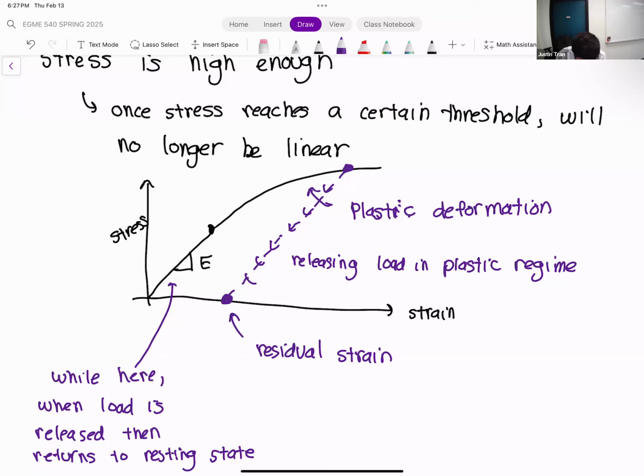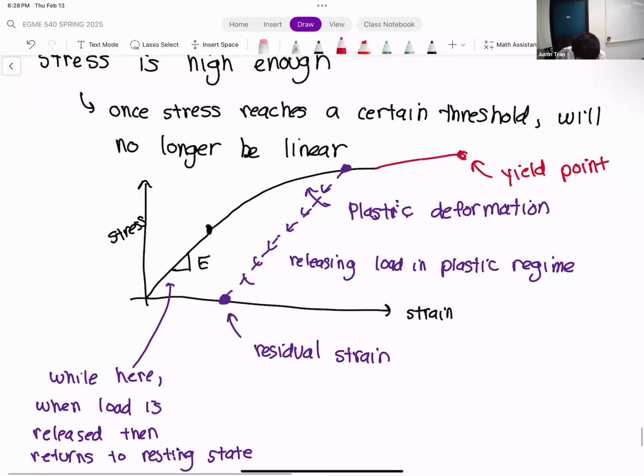Another thing that we account for is the yield strength of the material. That was in activity 2. Remember in activity 2, we said that the bike crank will fail if you reach the yield point. The yield point is usually somewhere out here, at a very extreme value of stress and strain. The yield point, or the yield stress.